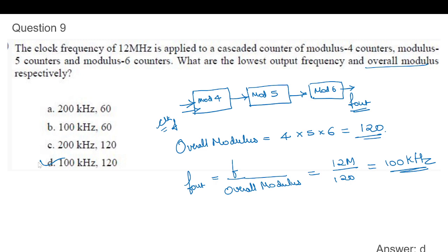Next, we will see the mod 3 counter. The mod 3 counter will take one input, which is the clock, and the output will be A and B, a 2-bit output, because it has to count 3 states. So 0 0, 0 1, 1 0, then back to 0 0, are the valid states. Then let's design.